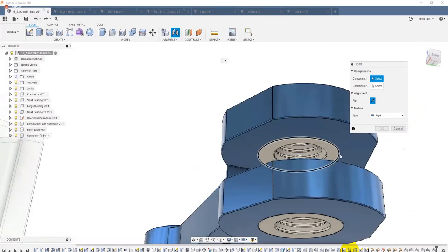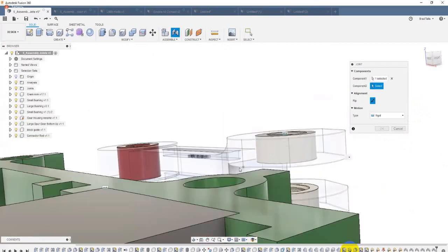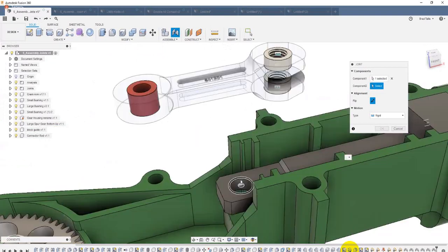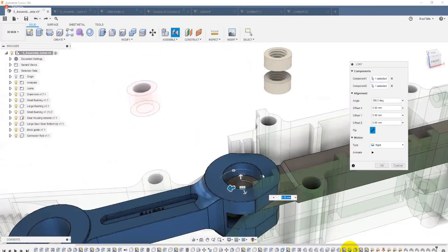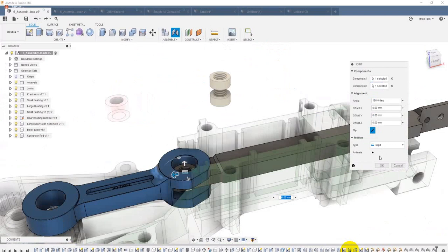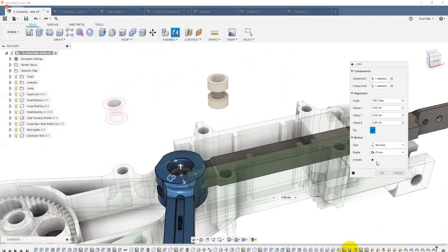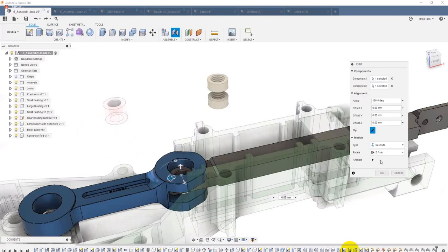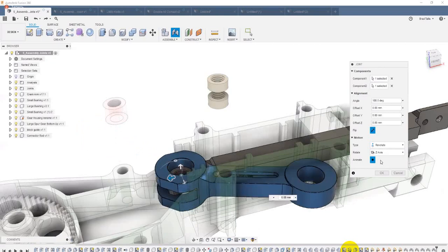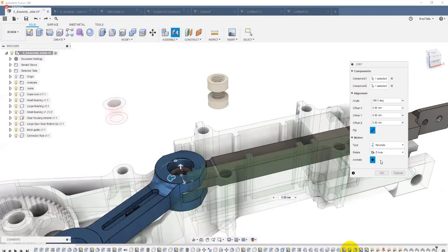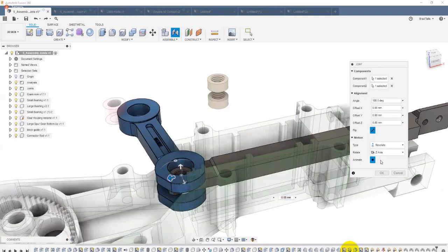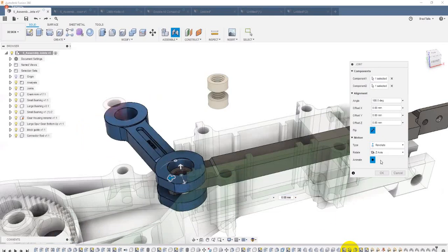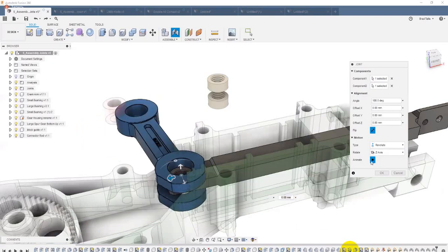Okay, now I want to do the same thing again. The other thing I noticed is when I positioned it, it kind of was a rigid. Well, I want it to be a revolute. So I'm going to say revolute, and you'll see it slicing through the object. Okay, again, it's just a quick animation to show it's revolving around the axis that I picked. But of course, it's going to cut through the model. So don't worry about that either.